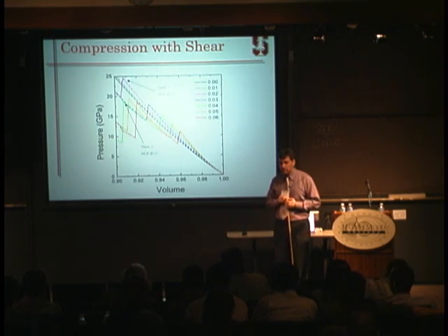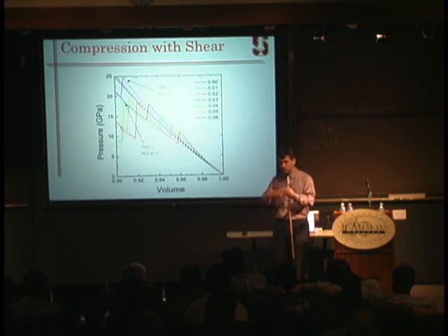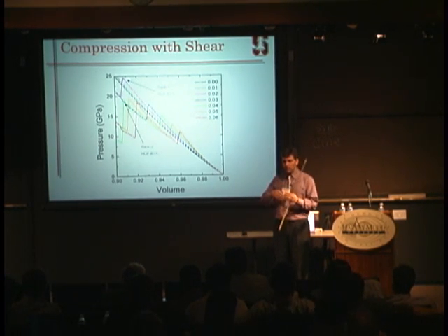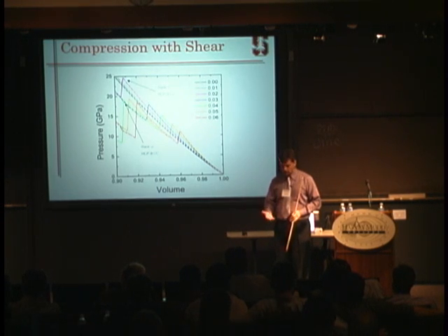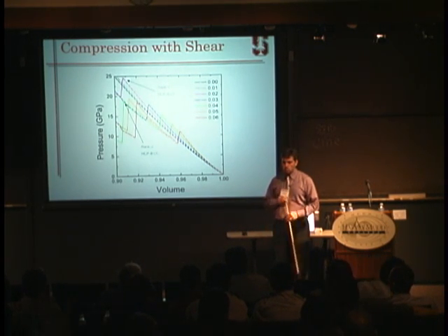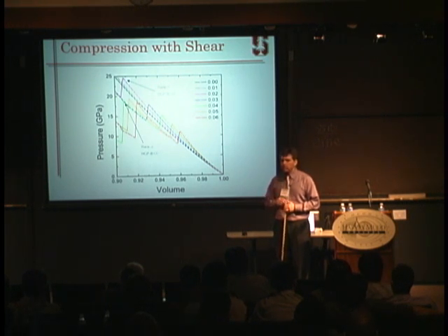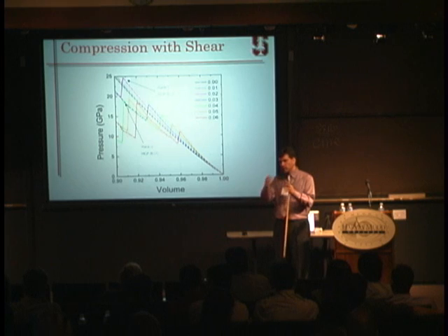Yeah. So with the computational realization, how do you make sure that you don't have numerical artifacts due to, let's say, mesh alignment? No, there is no mesh alignment, because we build these microstructures. That's what I'm telling you. There is no finite mesh. We parameterize, if you want, these sequential laminates, and optimize in that space of sequential laminates. Yeah, but don't you effectively have to pick some directions in this space? No, well, you optimize in the direction. So you have to optimize over the normal.